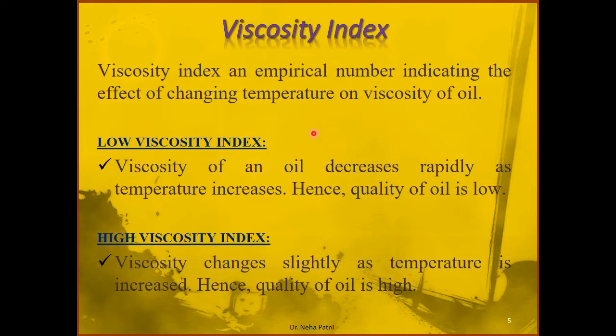Now if the variation of viscosity with temperature is very high, meaning it is decreasing rapidly, that means the liquid becomes thin and it may not remain in position. So we may say that the quality of oil is low, and we'll call it a low viscosity index oil.